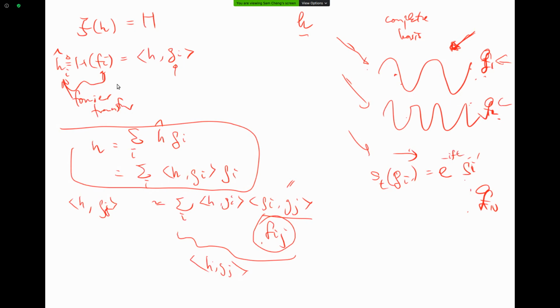But you see, if I look at this as a linear operation, if I model this shift operator, I mean the entire thing, if I vectorize that, this operator becomes a matrix, and this signal here is a finite vector. Here I'm drawing it continuously, but if I discretize it, it becomes a vector. Let's say I just use Gi here. And then this thing is just multiplied by a number, maybe lambda, times Gi. Then what you see is that this Gi is actually the eigenvector of this shift operator, or shift matrix operator.